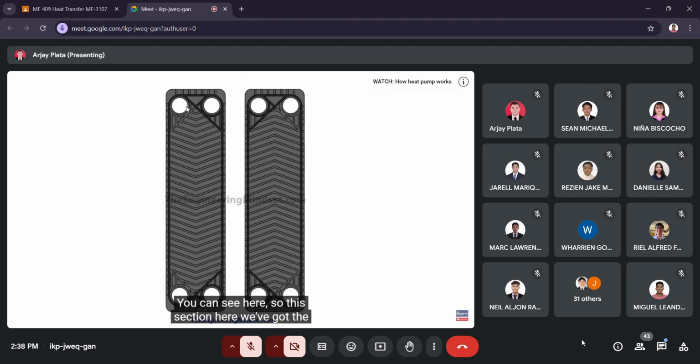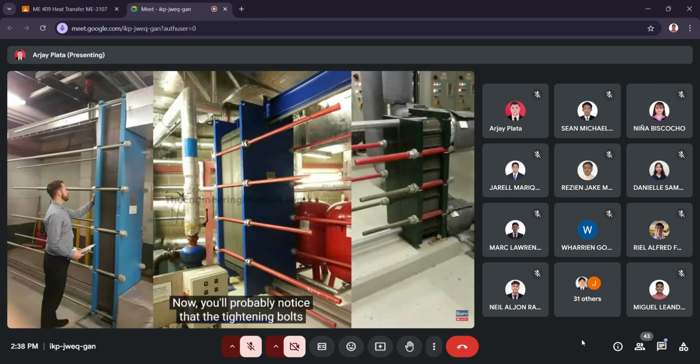You can see here, in this section, we've got the rubber seal coming across and a double seal on this one, so that no fluid in this can leak out or flow in, as well as this side, whereas here there is no gasket, so the fluid, if it entered here, could flow down and enter into this one because there isn't anything there. Same as this one, the fluid can only come out of here and travel up and then into this section here, into that hole.